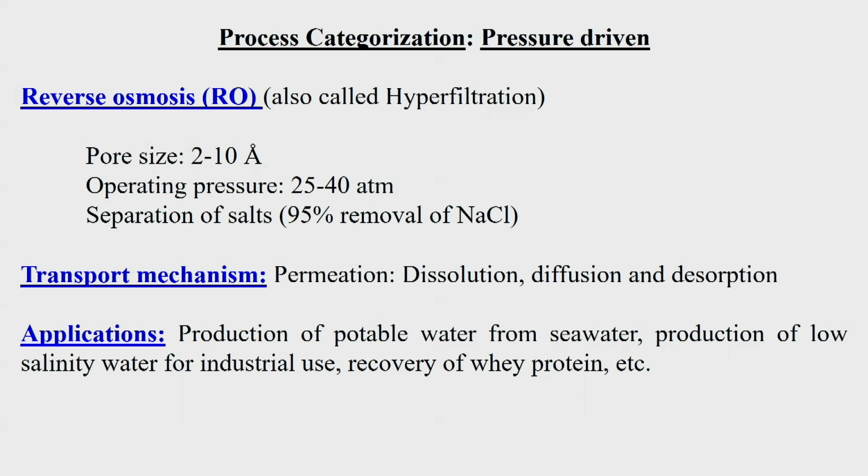In reverse osmosis, most of the solutes are retained, but due to the high operating pressure, the operating cost is to some extent high, and to withstand this high operating pressure, the base material should be strong enough to withstand that high pressure condition.